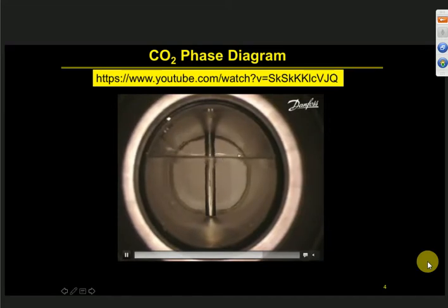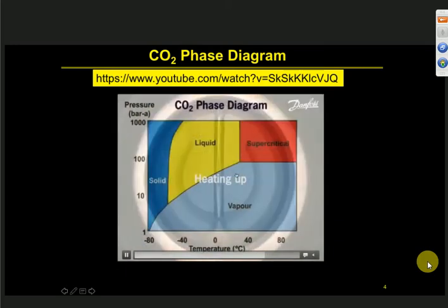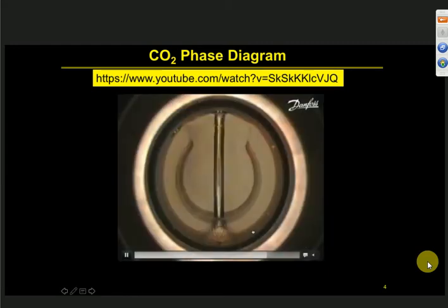in this case, instead of opening the valve like here, you heat it up. So as you heat up, here at room conditions approximately 20 degrees C, and then you heat up to greater than 31 degrees C, and right around the critical point you see that there is no phase boundary, that line that you saw between liquid and vapor.